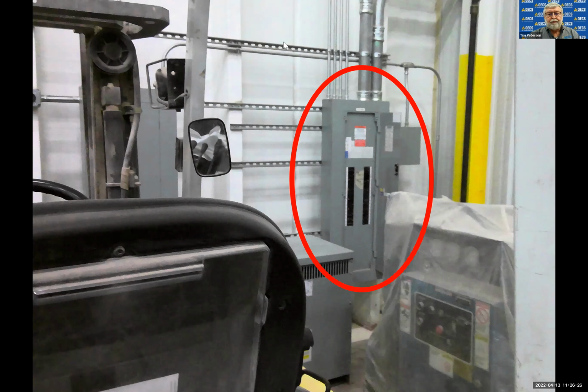So again, the comment says the National Electrical Code does not require a door to cover breaker handles. It does not require that. Yes, there's a fine line between the National Code and what OSHA is looking at. OSHA is also looking at the environment, reducing the dust factor and accessibility to it.